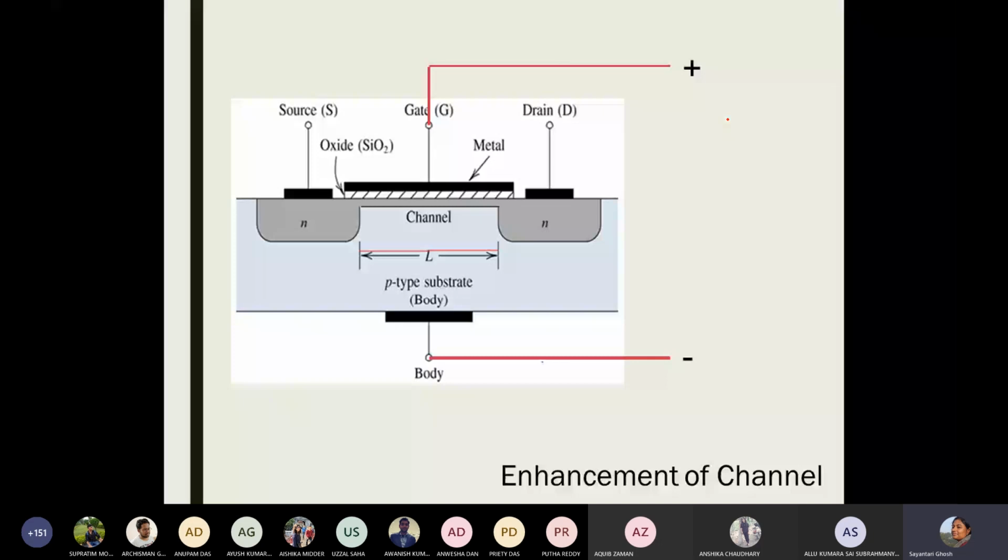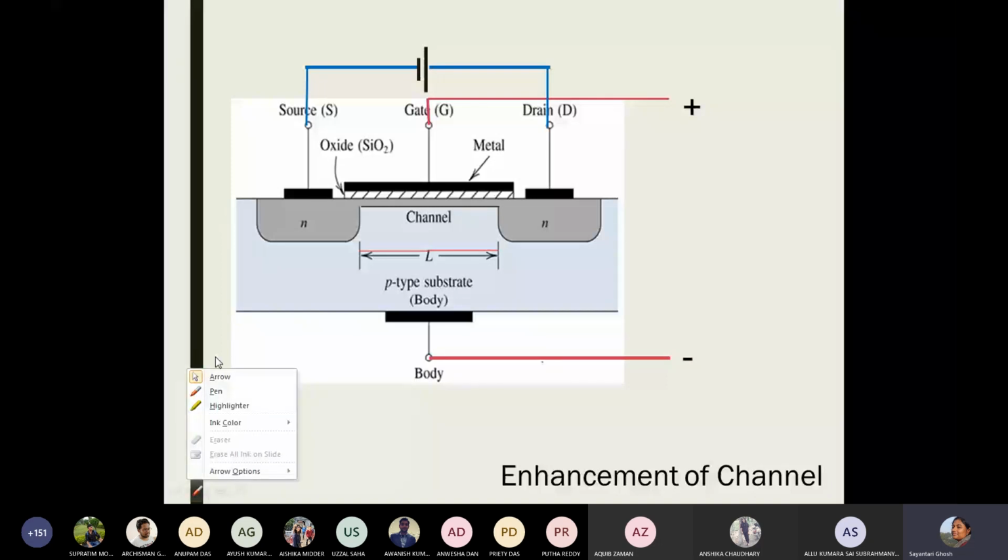The rest of the story is quite similar to what we had previously. I must connect a battery between drain and source, to attract the electrons sitting in the source and make them flow to the drain. I attach a battery between drain and source, where the drain terminal is kept positive, just as before. Now that the channel has been enhanced, electrons will flow, and the current will also flow in the appropriate direction. This is my VDS, the same as the VDS in my JFET. A similar battery is attached here as well. This is also called VDS, causing the drain current ID.